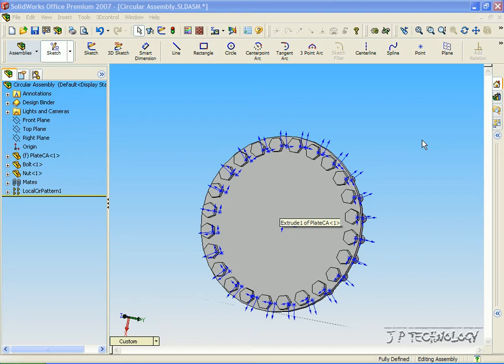This is tutorial number 73, and it covers how to use the envelope feature within SOLIDWORKS. Now, what an envelope does in SOLIDWORKS is it's a body or a shape that you've created as a part. You bring it into an assembly, and you're able to see if a part or a component or assembly that you've already made fits into a certain area.